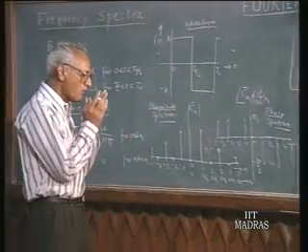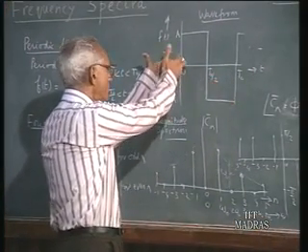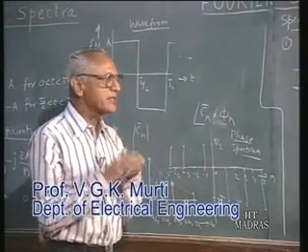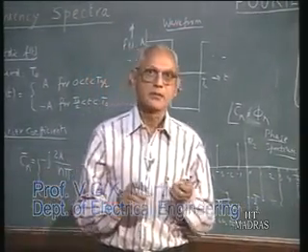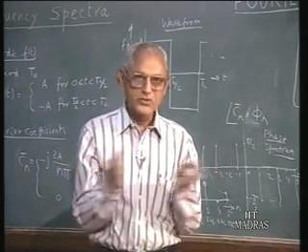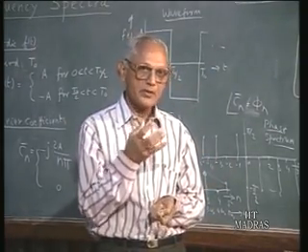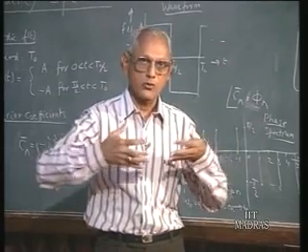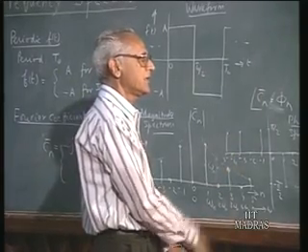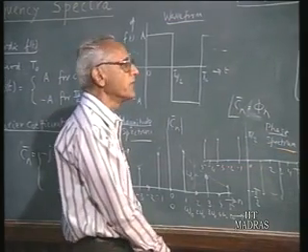So the conclusion that we draw from this is, if we have a square wave, whether you put the origin here or somewhere here, the magnitude spectrum will remain the same. So if you have a periodic function, the ratio of the amplitudes of different harmonics will remain the same irrespective of where you pitch your origin, because that is a fundamental property of the waveform, how different harmonics can go together to compose the given wave. So the magnitude spectrum remains invariant under translation in respect to time, but the phase spectrum undergoes a change depending upon where you put the origin.